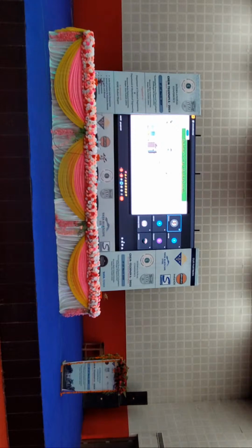So decoupled power and energy, and deep discharge and charge capability, are important features. It is capable of 10,000 cycles, or you can say the life can be more than 20 years, right? And the chemistry is a very simple thing. This particular battery is the vanadium redox flow battery.